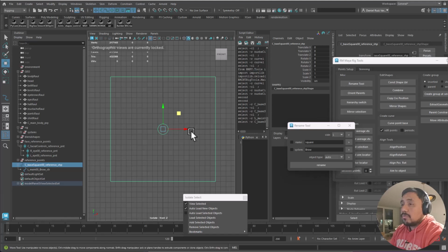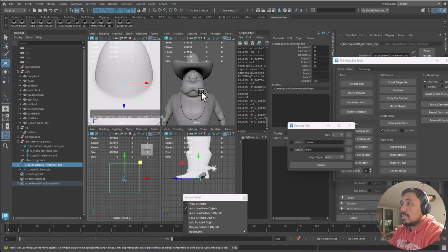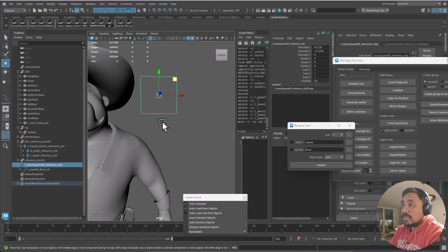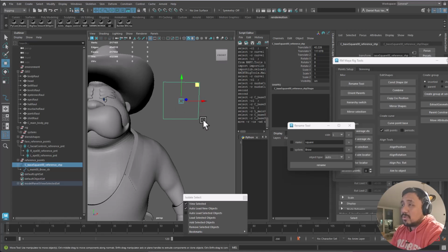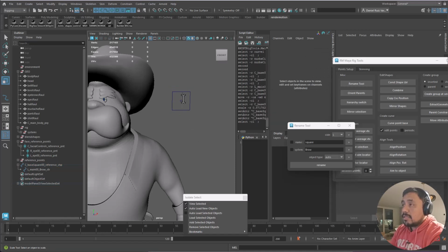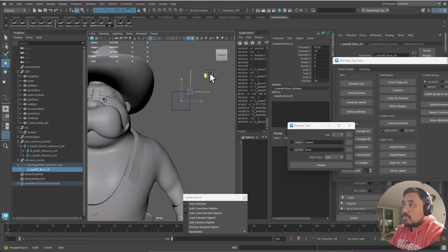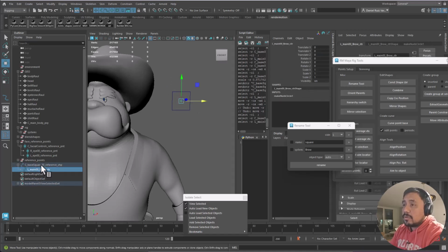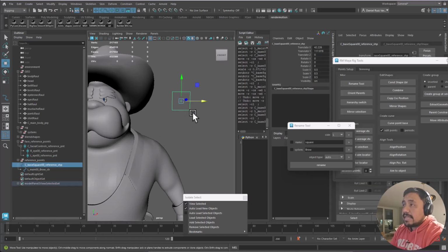What's important to understand is that now I can take this one, and of course maybe it doesn't match the character, maybe it's too big for the face. Well, actually the size is pretty good, but I could make it smaller. If I scale this one down, notice I'm going to scale it 0.5 and put it here. This control can still move here, and the values go from 0 to 10, even though it's smaller. The reason is that it's scaling the space of the child, and the child is the control, and this is the parent, and it's scaling the size.